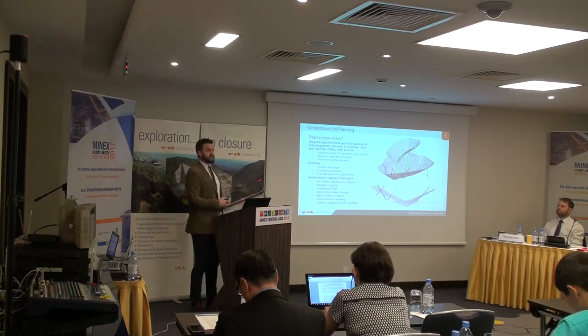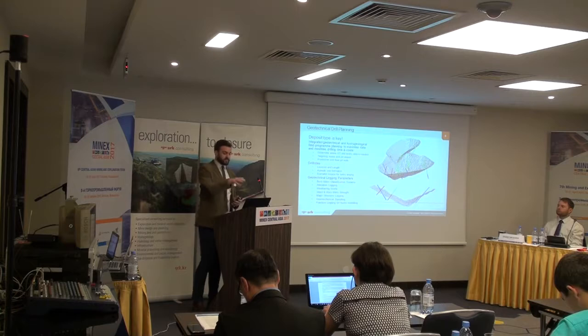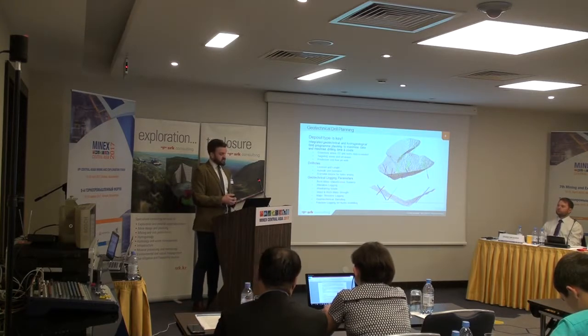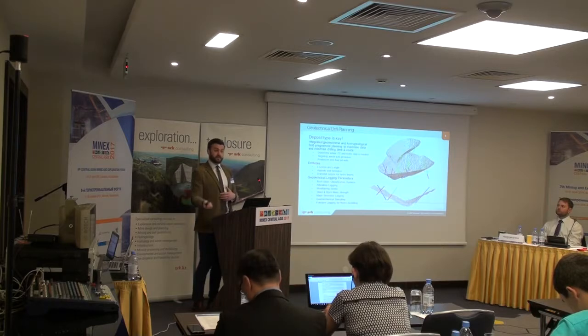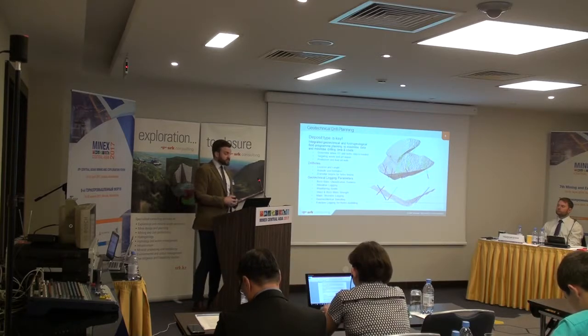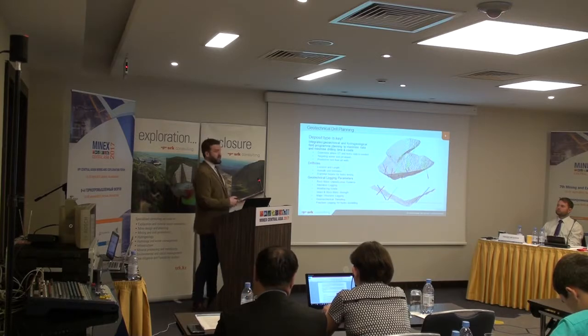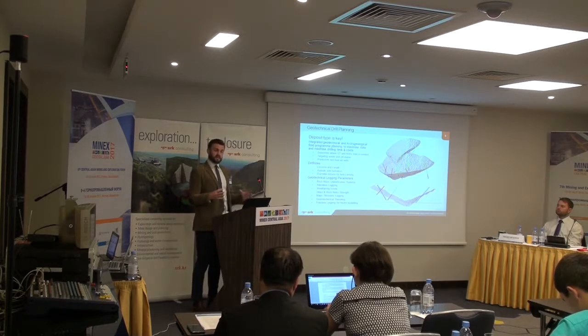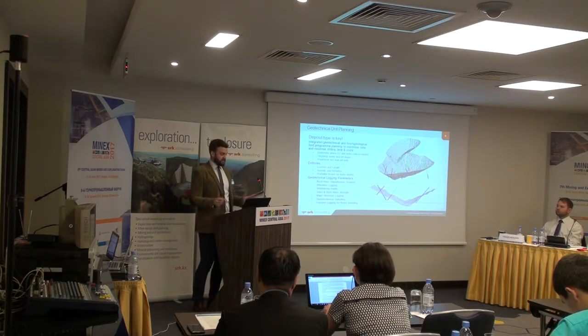Second thing you need to think about is azimuth and inclination. If you orientate the hole for your resource drilling, you can then use it as a geotechnical hole and collect structural measurements. And the third thing I have there is diameter required for hydro testing. Normally the holes need to be slightly larger for hydro testing, and these holes should be considered when planning any kind of field investigation.